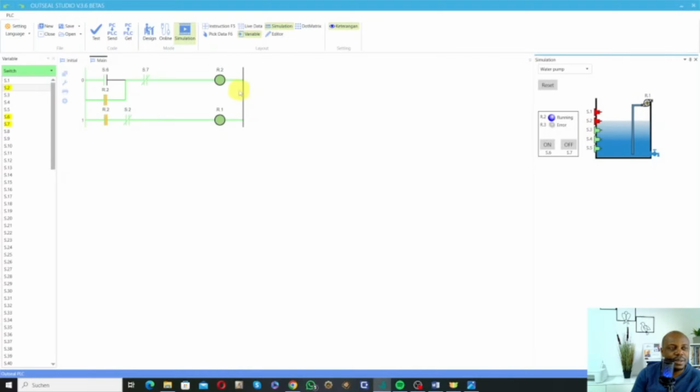That is because this running light is on, and when the water gets to this place, it stops. This tap is always bringing out water, so the level drops. Because the level has dropped beyond this place, the pump starts working again. It gets to this place, it stops. The cycle time is very, very short. If you run your pump like this, the pump is going to burn. So you need to design it in another way.